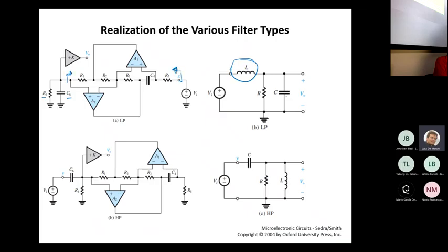All this part is the substitution of the inductance. Here we have the output voltage, this part, but we need the buffer to decouple the load with respect to the node of the LCR resonator.